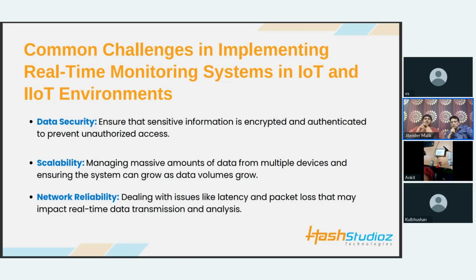We can also do certificate based MQTT. If you want to directly transmit onto an AWS Greengrass device, you can do that from this device itself. Other than that, you can set up your own private Mosquitto server, and we can transmit data onto this.